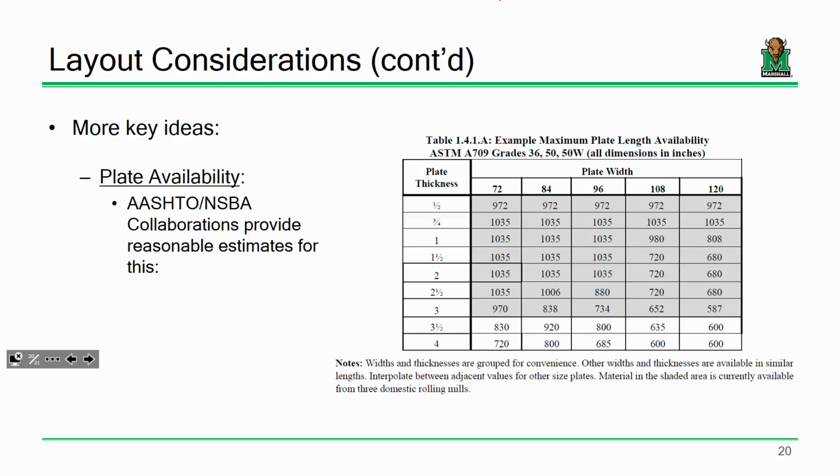What is the most optimum selection? Everybody okay with this? Okay. Don't spec out a plate that's not standard, okay? You start asking mills or service centers to produce plates that aren't of standard size, they're going to bump the cost up and they're going to bump the time up. So don't do that, okay? Everybody all right with that?